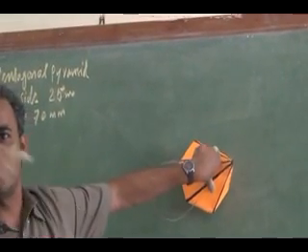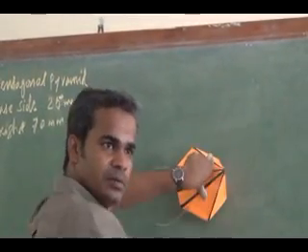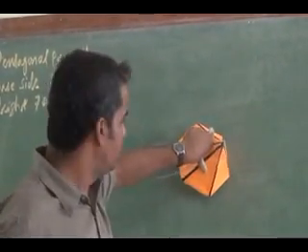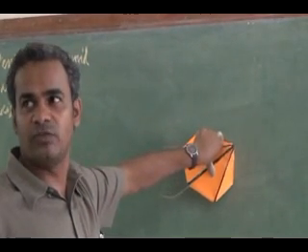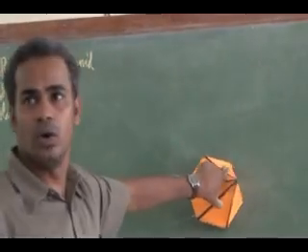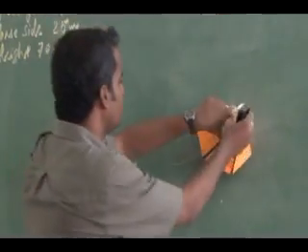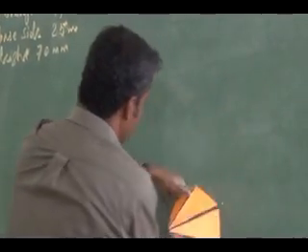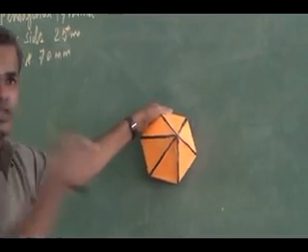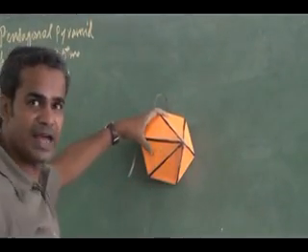The slant edge containing the base corner is nothing but a line. If it is perpendicular to VP, it has to be parallel to HP, right? So draw the front view and top view of the pyramid. Now, how is it? It is like this. In this orientation, what about the axis of the solid?